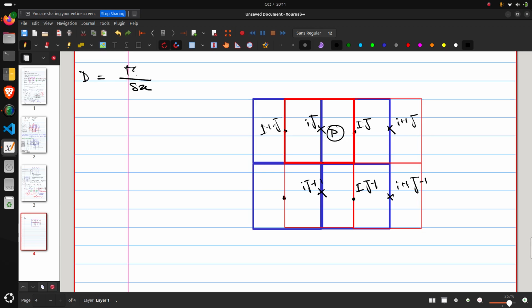So here this is the south face, right? And the gamma, if we need it, what is the gamma here? We will need gamma at this point. Delta x is already known, but how will we know gamma at this point? We said that all the scalar variables like gamma, rho, temperature and pressure, we will store at these points, right? So now, rather than taking an average of 2 points, we will take an average of 4 points.